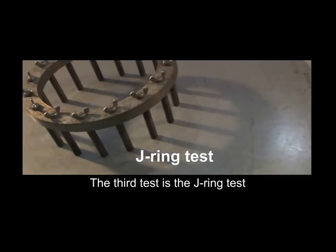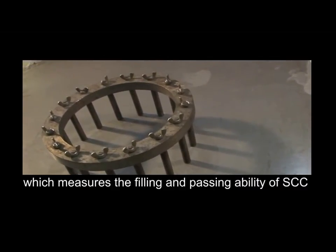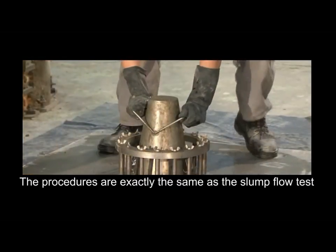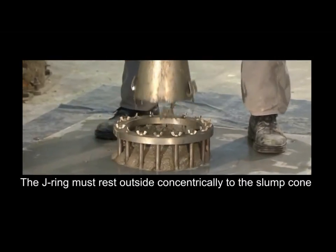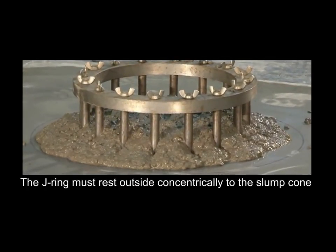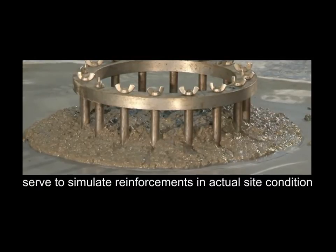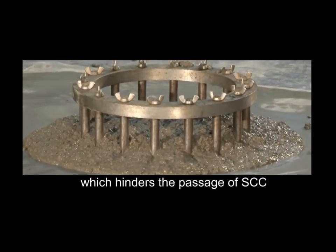The third test is the J-ring test, which measures the fill-in and passing ability of SCC. The procedures are exactly the same as the slump flow test, except that a J-ring is used. The J-ring must rest outside concentrically to the slump cone. The steel bars of the J-ring serve to simulate reinforcements in actual site condition, which hinders the passage of SCC.